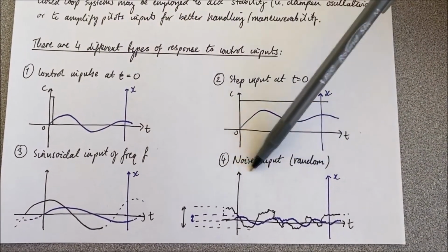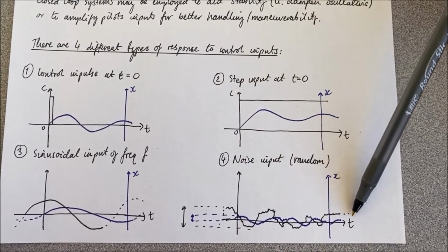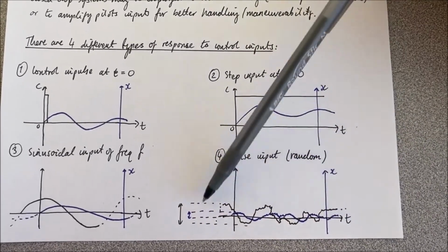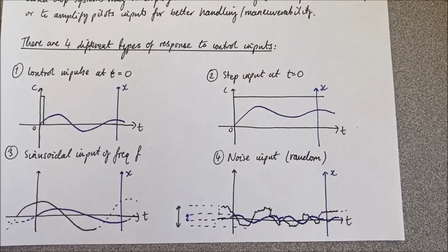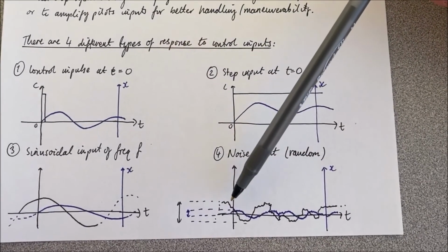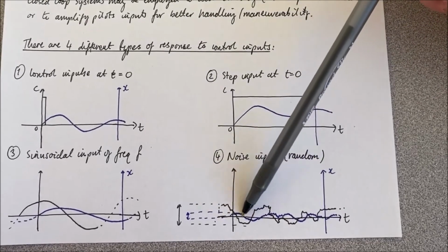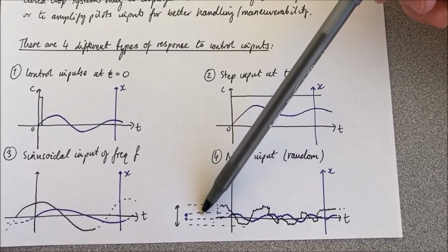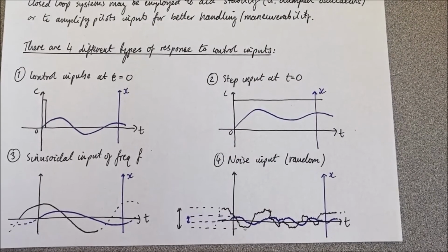It's basically noise, it's random, or you can think of it as like the perturbations in alpha or beta during regular flight, which the aircraft has to deal with, turbulence and that kind of thing, right? So in this case I've drawn a random control surface input, and then the blue line, which is the output, again slightly lags but is damping out those perturbations.